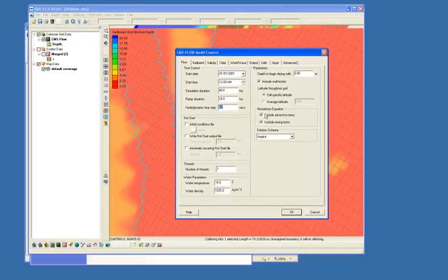There's a hydrodynamic time step, and normally when you build your grid for the first time and you're happy with it, the first time you come into model control, a value is normally showing here. This time step is actually what we consider an explicit time step, so it would be on the order of a second or less.